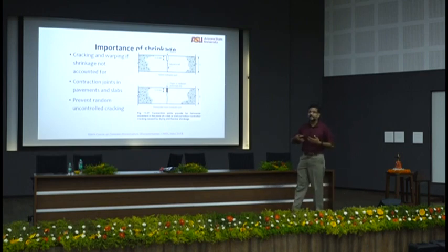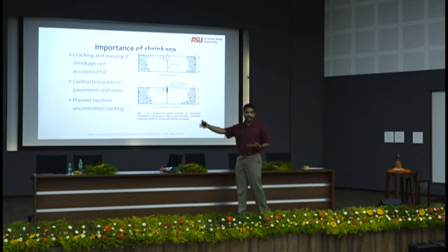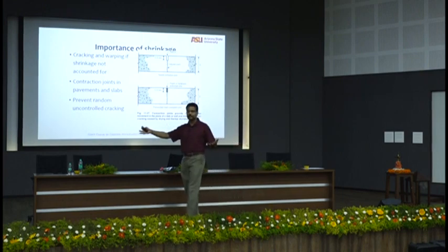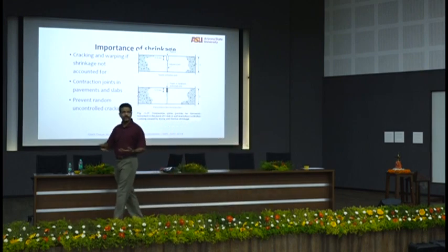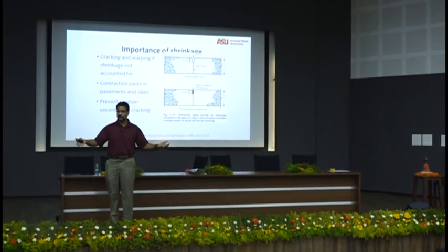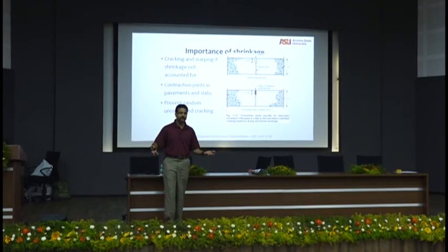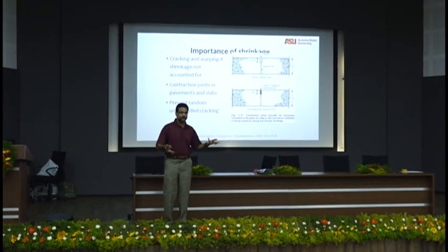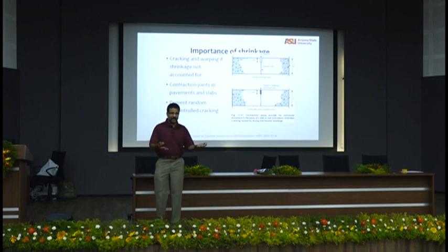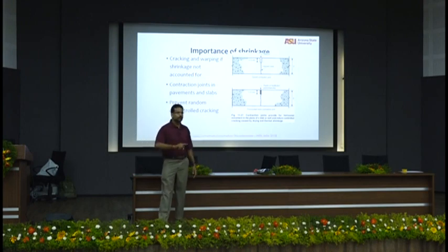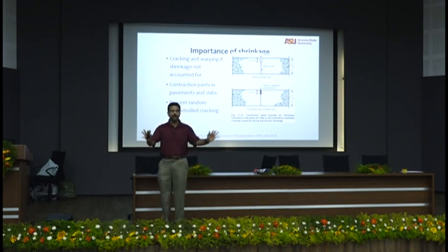We do a lot of slabs in the US, right? A lot of slabs on grade. Pavements are nothing but slabs on grade. Remember your Westergaard equation for slabs on grade? Simple Westergaard equation, a slab as a plate on a flat foundation. So it's a very similar idea. If you do that, you have a lot of cracking and warping, right? When temperature changes, between day and night, you can have positive and negative curl and warp. You can have a slab curl, slab warp, curl, warp.